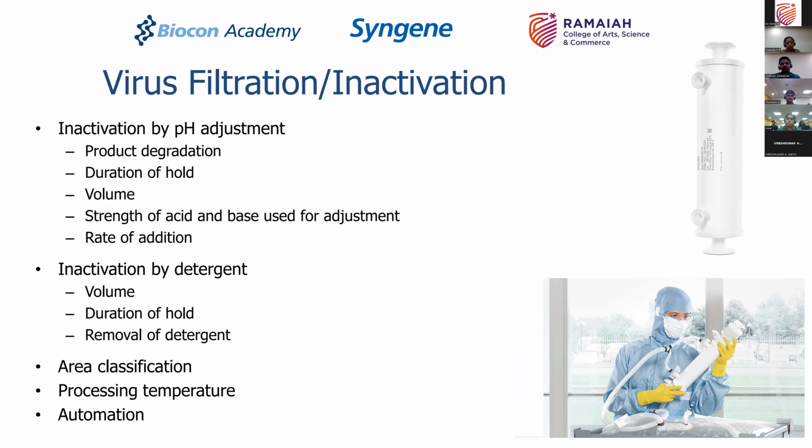You do inactivation by pH adjustment, as I said, where when you do a pH change, you have to worry about whether the product will degrade at that pH. What is the duration of hold? What is the strength of acid or base used? What is the type of acid and base used? And what is the rate at which you are adding it?